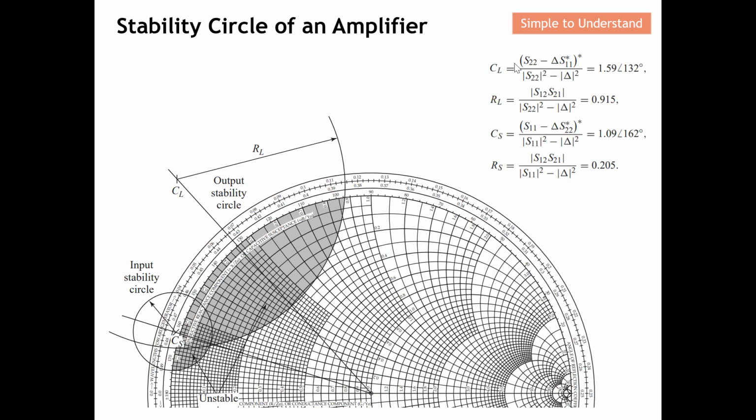Next over here, you see that this center will be equal to 1.59. How can you go about it? Because the size of the Smith chart actually varies, the first thing that you need to do is measure your Smith chart.